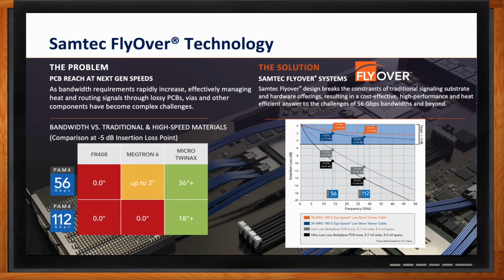In addition, as data rates get faster, one of the design approaches that engineers can take is to add a retimer or CDR. Basic signal integrity: if there's too much loss, the eye of the signal closes. And by putting in a retimer or clock and data recovery, the eye of the signal opens back up. A lot of companies use that, especially for long traces on PCBs. It's a tried and true method, but it's expensive. It takes up PCB space. You have to worry about the power for those as well. Long traces, lossy elements that the traces have to go through on a PCB, via multiple connectors, whatever the case may be, Amelia. So taking that signal out of the PCB, putting it into the ultra-low skew Twinax is really the solution to the challenge that we see.